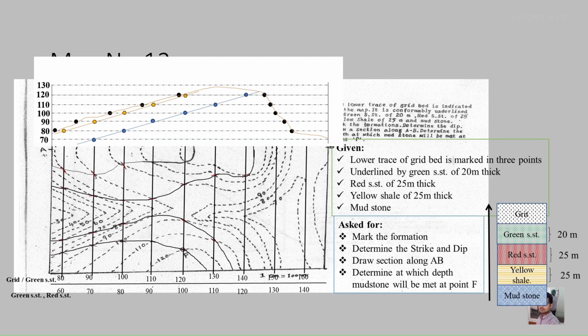So if you want to do for the next beds, what you can do is you can move this point further down by 25 meters. So this is 10, this is 20, this will be 25 at the middle of the line. In the graph line, you will be having the mid lines also. You can use that if you want. Like this, you can draw the profile for all the other beds. Okay. So what we drew is the profile of these two bedding planes.